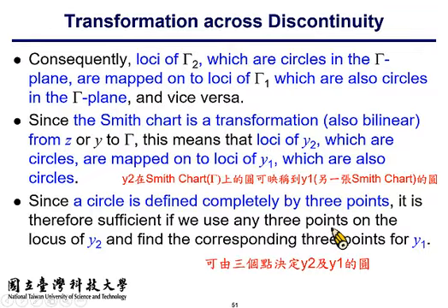So consequently, on the Smith chart the locus of the transmission line is a circle, which we call the constant SWR circle. As long as the transmission line has no extra loss, the magnitude of the reflection coefficient is fixed; only the angle, the phase of the reflection coefficient, may vary at a different position on the transmission line.